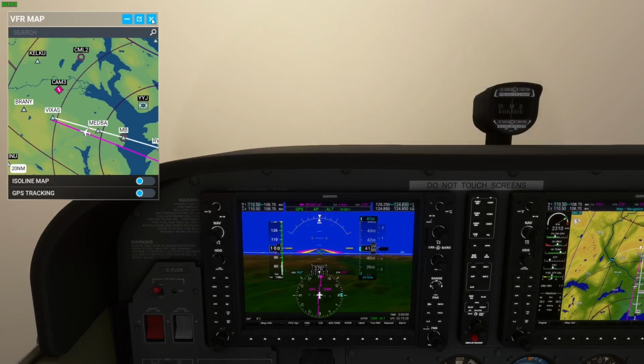GPS, of course, is much more versatile because it'll take you right to a certain waypoint. We're not using non-directional beacons and an ADF to detect them, or VORs. The GPS takes you right there. Now, when it shifts to green, the navigational equipment automatically changes over to the radio precision instrument approach, or ILS, which is what we've used for years. And that's still more precise than a GPS to bring you right down to the threshold of the runway.